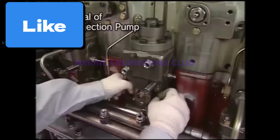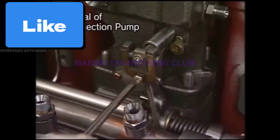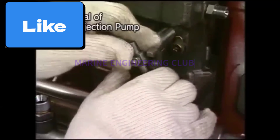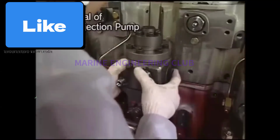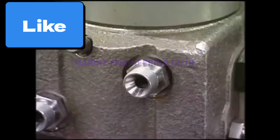Bring it to your workshop. Now this is what is removing your fuel rack. Different mechanisms will be there on board your ships. Lift it up. If it is becoming very difficult to pull it up, what can you do? Chain block. Use a crowbar. Put a sling on it and turn the engine, so your camshaft will push your pump up. The nuts have been removed. Then you can lift it up if it is not heavy, otherwise use a chain block.